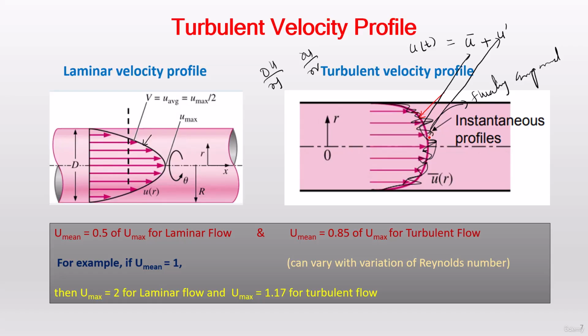So that is one approximation that you get in CFD, the truncation error, that is a mesh error, where you are leaving the high order derivative terms in your equations, and also you have the finite size of the cells. It cannot go to zero. And the second error is coming from turbulence. So that's why whenever you solve through RANS, you can expect an error in a range maybe from 5 to 15%. So I always try to keep the error less than 10%, but sometimes it may be higher depending on the flow nature.